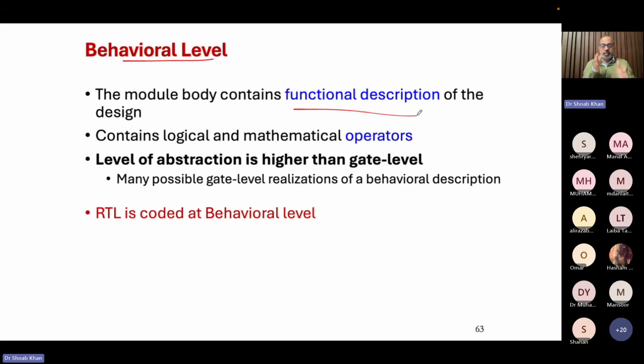They are algorithmic registers, but they are storage elements that have to be instantiated, whereas in Python there is no such concept. That concept is the main thing we need to learn: what is the value of a register in hardware. Otherwise, Python is almost as good as Verilog, but not really, because that would make a big combinational cloud, which would take forever to complete the execution.